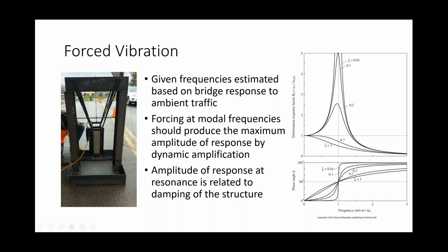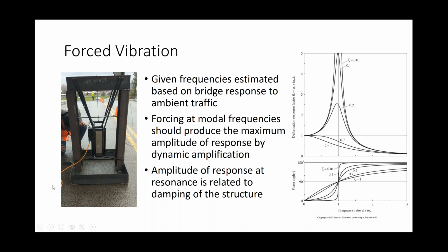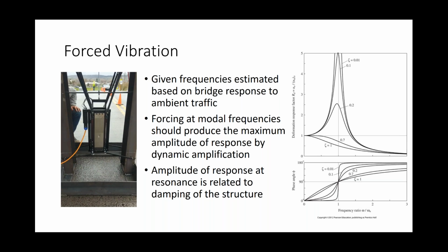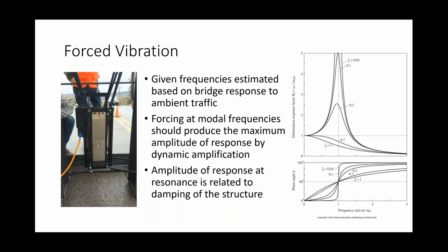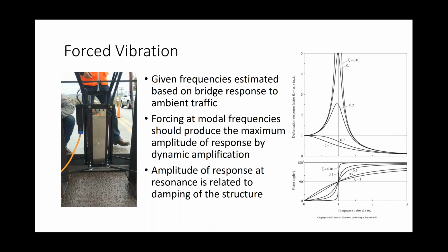Forced vibration required us to build this shaker frame. You can see here we're driving a very specific mass at a specific frequency, and that allows us to vibrate the structure and look for this natural frequency.